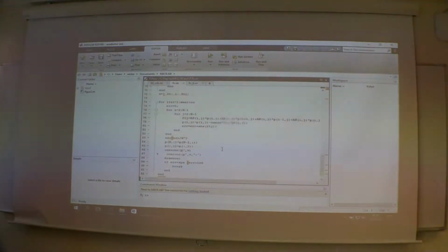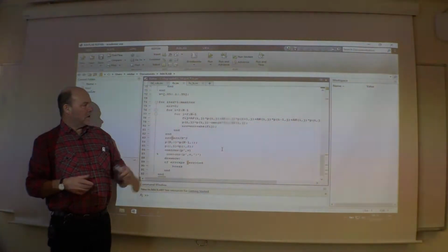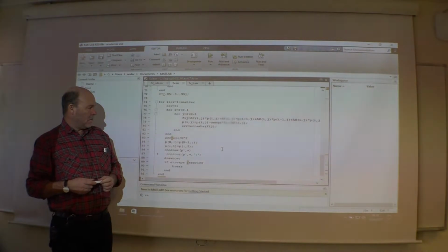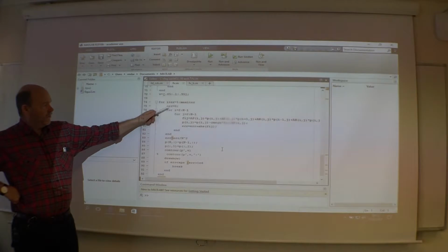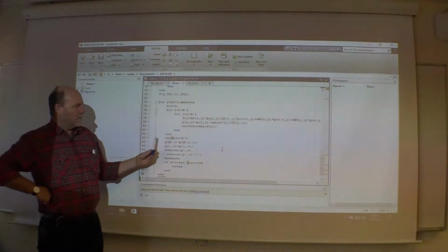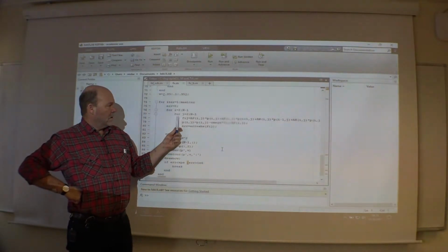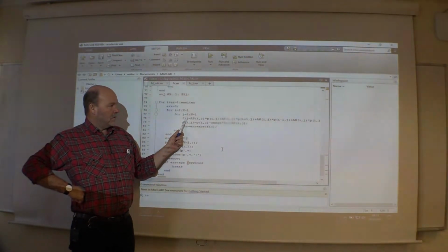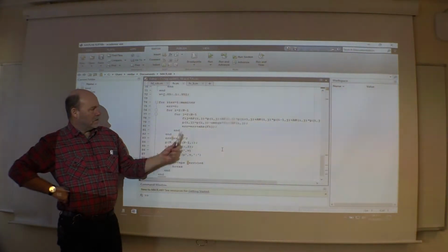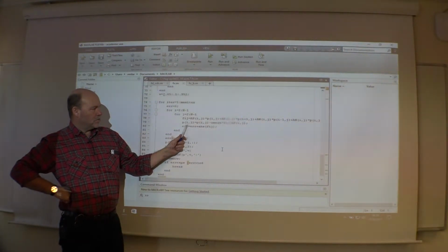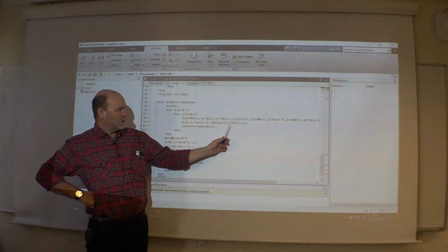And then finally we do the iterations. So we have to find a solution somehow. The equation system for the entire domain is given by, if you can recall, the modified Newton-Raphson for SOR. You calculate a residual, which, if everything is okay, should be 0. And then you use the residual to adjust your phi according to this recipe here.